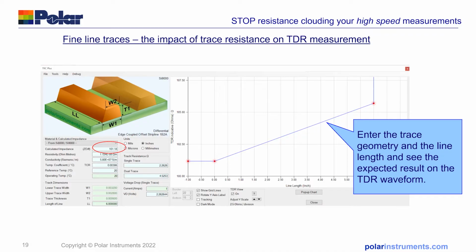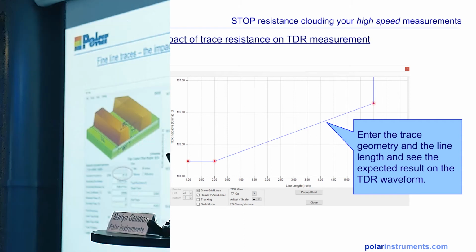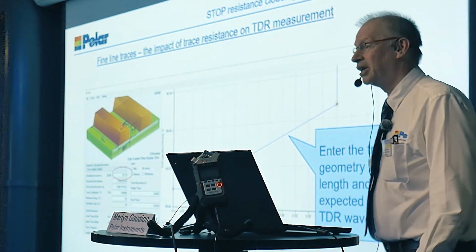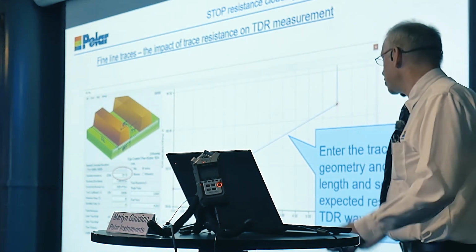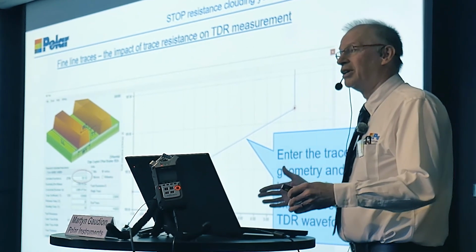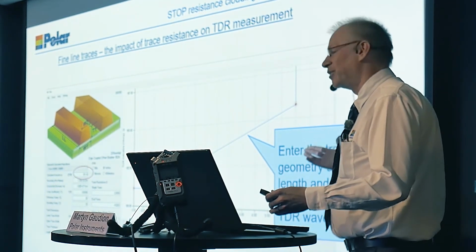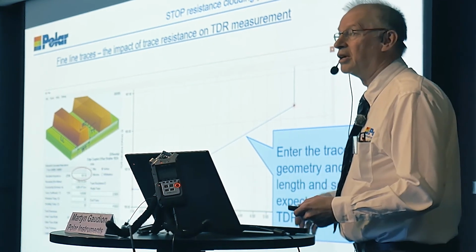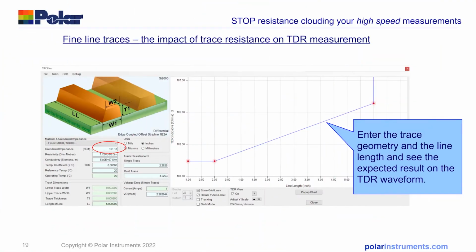But you can see here, if you're taking the average measurement here, if you double the length of the trace, it's going to go from a 100 ohm differential pair to a 105 ohm differential pair, 110 ohm differential. Clearly, it's a nonsensical measurement, but we see this happening all the time. It's just because geometry sat at a level which were broad enough that this didn't come into effect until we're down to 75 micron lines and below, and the thinner copper substrates we're seeing now.